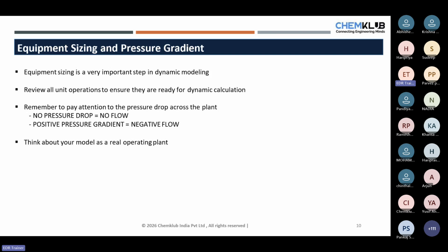Then these pulses are actually diminished by using a very large vessel to hold whatever pulses are coming. They are stored, sent into a very large vessel where it will dampen down the flow, and then a steady state flow is obtained at the outlet. You will get a steady state flow which is sent to the reformer as a fuel.